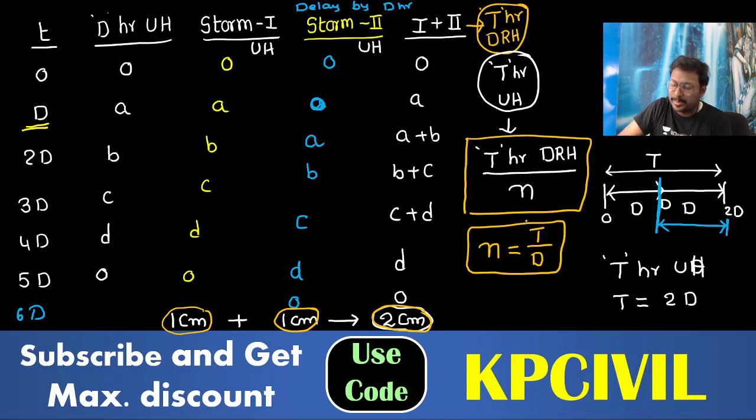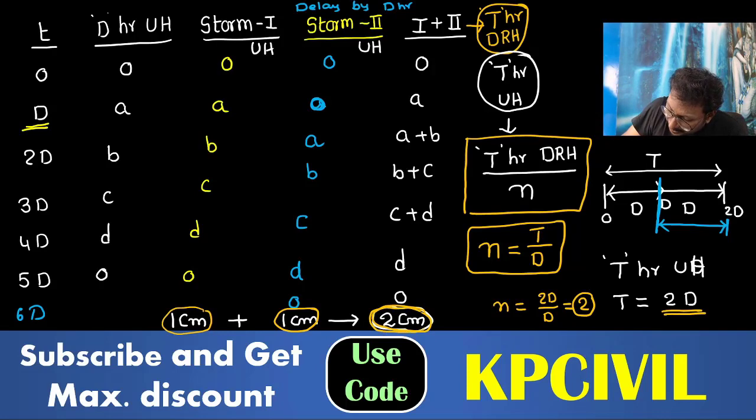T is 2D, so N is equal to 2D by D, which is 2. So divide by 2, because you are adding 2 storms of 1 centimeter depth each, giving a DRH of total depth 2 centimeter. You need a 1 centimeter UH, so you divide by 2.